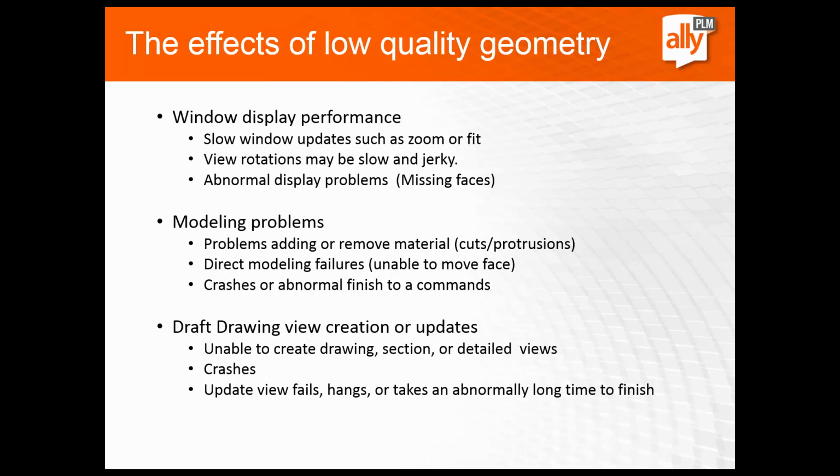There are also modeling problems that you might run into, whether that be adding or removing material such as cuts or protrusions. You may deal with some direct modeling failures, unable to move faces if you're using either the synchronous steering wheel or the move face command in ordered. And occasionally you may run into the problem of Solid Edge crashing or strange things happening when you're trying to finish a command.